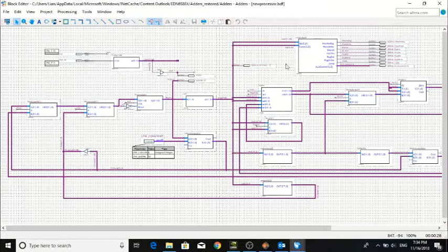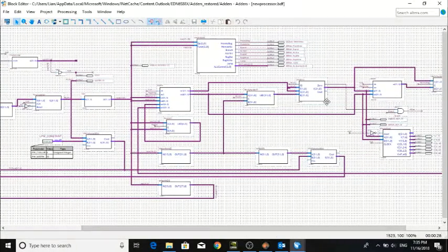The control unit takes in the opcodes and produces instructions based on these opcodes. Instructions are then used to control the ALU and switches off and on various multiplexers. This is our ALU, which performs arithmetic and logical operations based on controls sent by the control unit. The 0 output here returns 1 when the output of the ALU are all zeros.